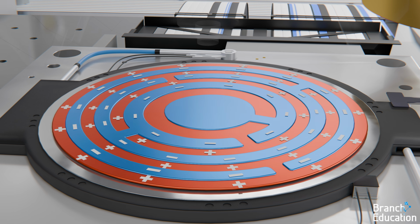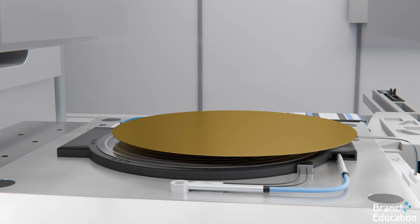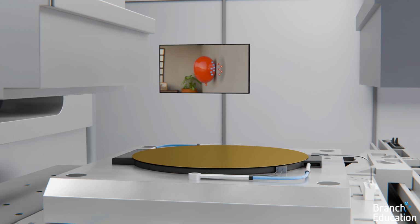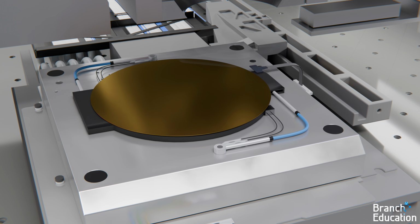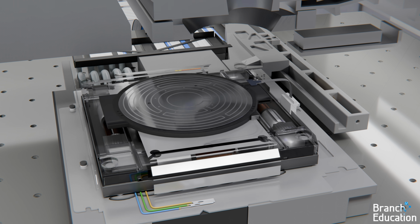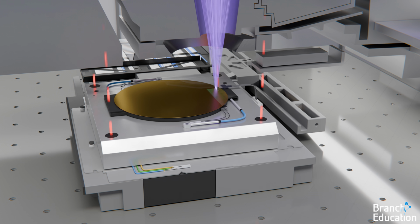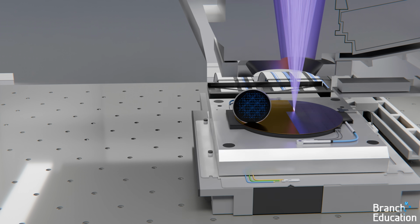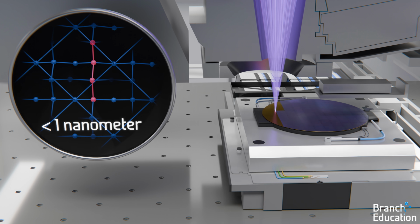The clamp cycles zones of high voltage across the backside of the wafer to keep it in place, a phenomenon similar to sticking a balloon to a wall using static electricity. To reach nanometer-level accuracy, the plate is independently moved using smaller motors, which is called the short stroke stage. By combining the long stroke and short stroke stages along with measurement encoders, the machine can quickly move the wafer as it's being patterned and maintain an accuracy of less than 1 nanometer, or approximately 4 silicon atoms.